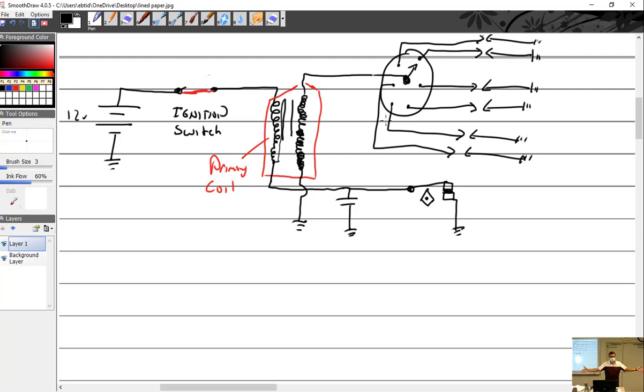And it's now that field, that force field, or magnetic field has cut across the secondary. But it really hasn't done anything, right? Because it just built up. And believe it or not, that's not when we're going to use it. So it built up, and it's just sitting there. So here we've got this field that has grown, and it's encapsulated the primary windings, but it hasn't done anything to them yet. So it's just sitting there. So what's going to happen is this cam is going to come around and start to open those points, right?